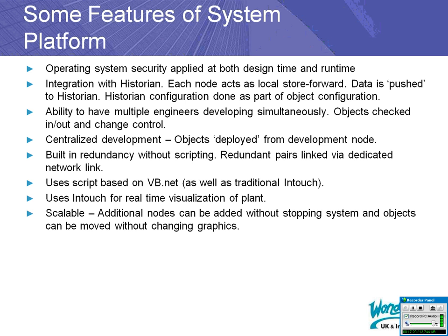It's scalable. Once you've purchased the System Platform, and I'll go into licensing later, you can then add additional nodes just by purchasing a platform license, and you can move objects between nodes. When you move those objects between nodes, you don't have to then go to your SCADA application and point them at a different node. They know which node the data is coming from.